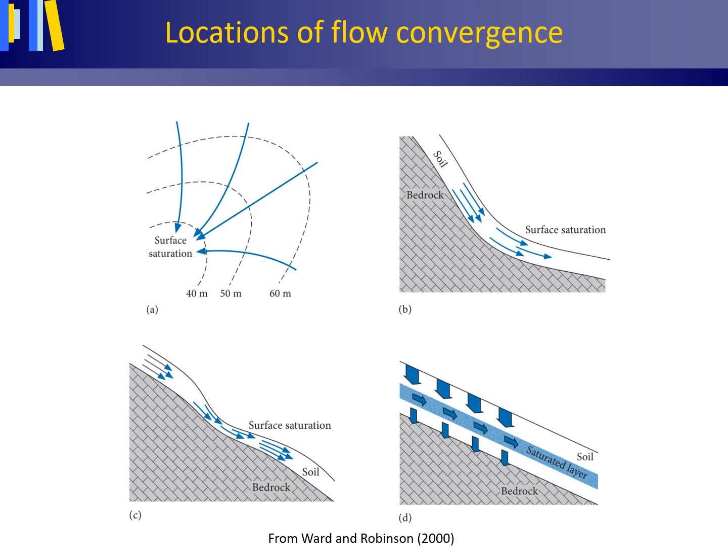Topographic convergence zones can be hill slope hollows or topographic depressions, that is, slope concavities in plan or slope concavities in section, as shown in this figure under A and B. For both types of concavity, through flow can enter such a concavity more rapidly than it can leave downslope, thereby forcing water to the surface. Also, where an upper layer in the soil that supports through flow becomes thinner, a perched water table may develop and rise to the land surface, as shown under C.